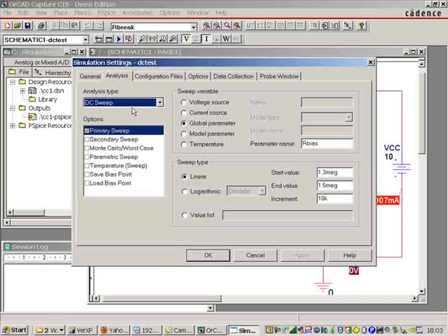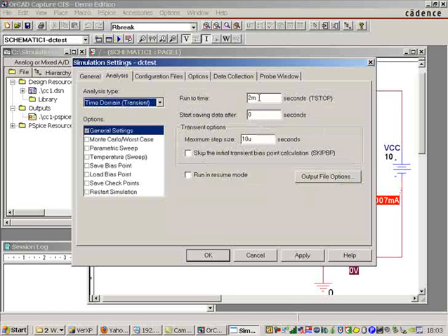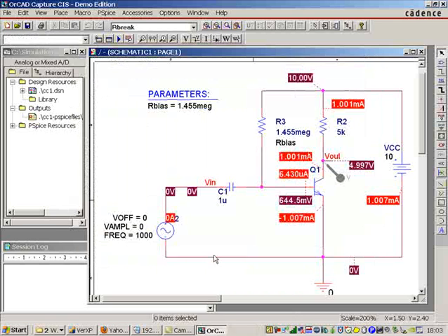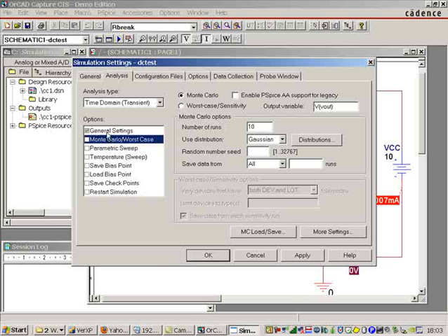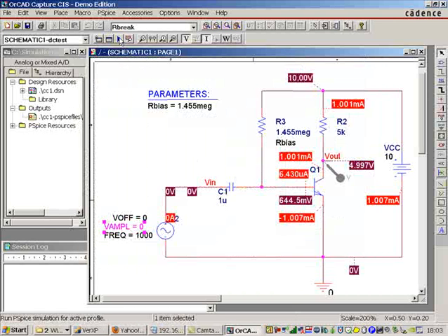Let's go to our simulation. We're going to do this time a time domain waveform for 2 milliseconds at 10 microsecond resolution. I've turned the input voltage to 0 because I actually want to look at the DC levels, so I'm not looking at anything else. I'm not running Monte Carlo yet, although I will do in a moment. So Monte Carlo is not turned on. Let's hit simulate.